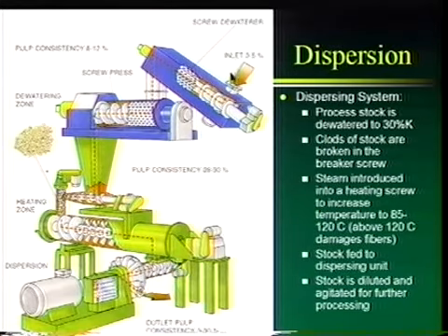First, we'll start off with a pulp around 3 to 5%, and that pulp may have already run through a low consistency thickener. Then we'll take that 3 to 5% pulp and use a screw dewaterer. So we've got a screw pressing that pulp, and a perforated cylindrical device here, and we're going to get our pulp to about 8 to 12% consistency.